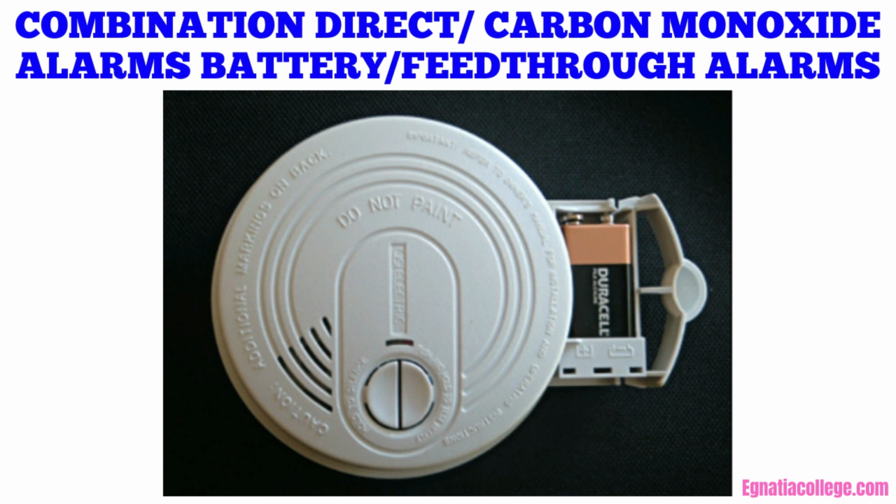The residence featured in this textbook has 4 smoke alarms, hardwired directly to a 120-volt AC branch circuit, S16. They are interconnected feed-through units that will set off signaling in all units, should one unit trigger. These interconnected smoke alarms are also powered by a 9-volt DC battery that allows the unit to operate in the event of a failure in the 120-volt AC power supply.